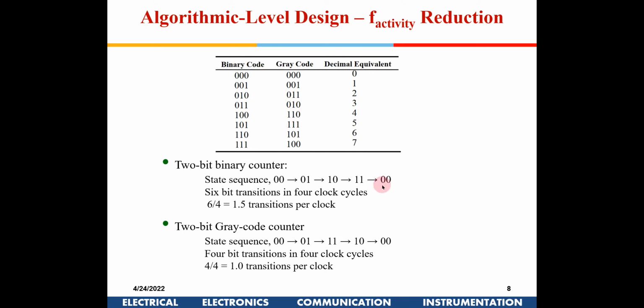So many a times we use counters and things like that. Suppose I am sampling an input at every 1 millisecond, where the clock is in gigahertz. Okay, I have sampled an input. Now when to sample the next? After 1 millisecond. So what will I do? I'll energize a counter, load some high value which is equivalent to 1 millisecond, and then wait for that counter to come to 0. Once it has come to 0, I take the next input, again load a new value into the counter, and then wait for that counter to come to 0.